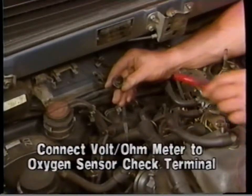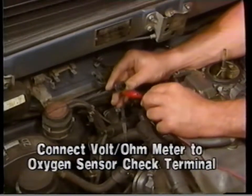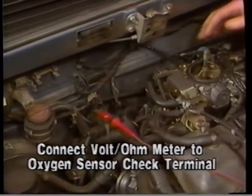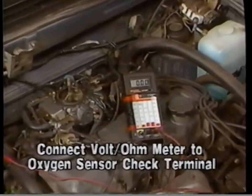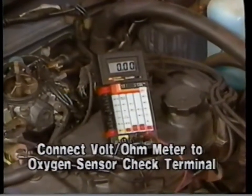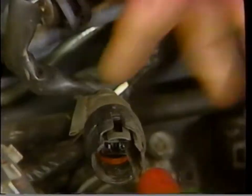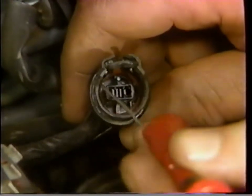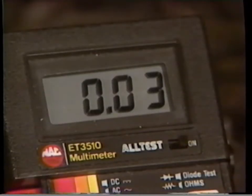After cleaning the carburetor, connect the positive lead of a digital volt ohm meter to one of the contacts on the oxygen sensor check terminal, and connect the negative lead to a good ground on the engine. With the ignition on, the volt ohm meter should show a positive reading. If the meter reads 0 volts, connect the positive lead of the meter to the other check terminal contact and recheck for a positive voltage reading.